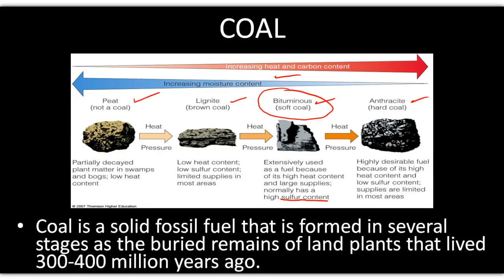So when you start talking about acid rain, that's the sulfur content. When sulfur goes up into the atmosphere, SOx and NOx we happen to call it, but if we're talking about sulfur, we're typically talking about SO2 and SO3. Just to make the comparison, we'll call it X instead of 2 and 3. So it's called SOx. When that mixes with water in the atmosphere, you typically will end up with H2SO3 or H2SO4, which we call sulfuric acid. So that is one of the problems in using coal in our power plants. But typically, a lot of our power plants have things called sulfur scrubbers, which take a lot of that out. We'll probably mention that some other time.